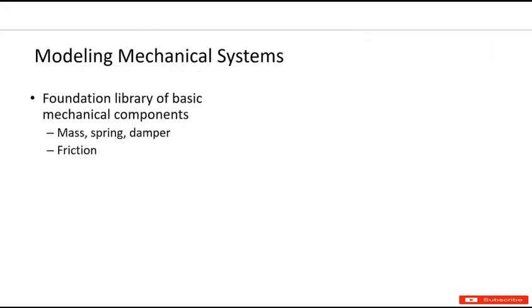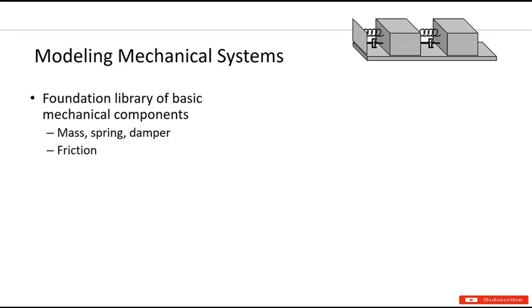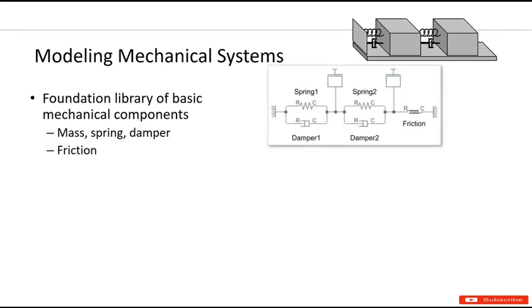So if I take each domain, just to show you some examples from each domain. If you were to model a mechanical system, for example a mass spring damper, a very basic mechanical system, in Simscape you already have the mass block, the spring block, the inertia and so on. You just need to connect it and then you can simulate it. It's very easy.